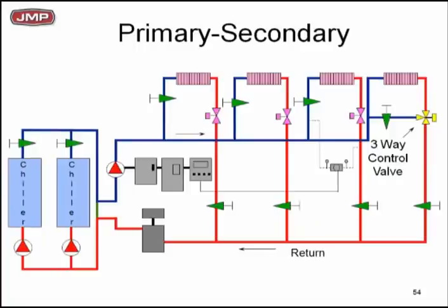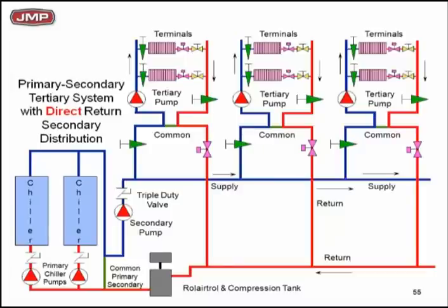Here's a typical primary secondary system we looked at. We've got a dedicated pump per chiller, constant flow. Again, see the common pipe? And you got a secondary pump with two-way valves. The secondary is variable flow. The primary is constant flow. Wow, here's that big chiller loop again, the big campus loop. But don't let this catch you off guard. Don't be confused by this. Remember that simple T-law. Remember the simple common pipe.